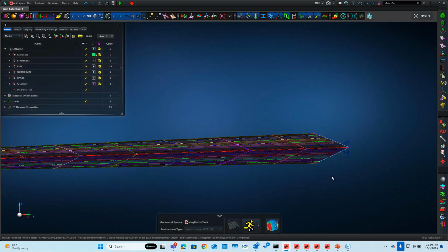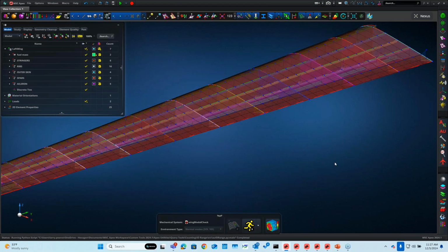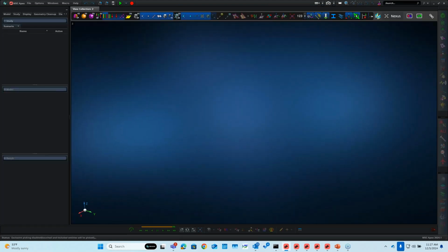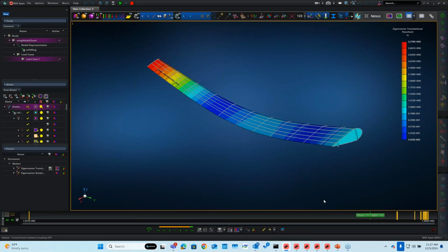The last thing that I might do is, once again, I want to verify my component, right? Is my component all connected together? Did I forget to equivalence or merge nodes? Or if I was using glue, did I actually forget to do the glue part, right? Because modules are completely self-contained, everything I need is here, okay? I don't have to reach into additional files, which once again, when I do that, I'm always asking, am I getting the right data from the right file at the right time? And anytime I have to ask that many questions, I really think that leads to the potential for errors. And once again, I am accountable.